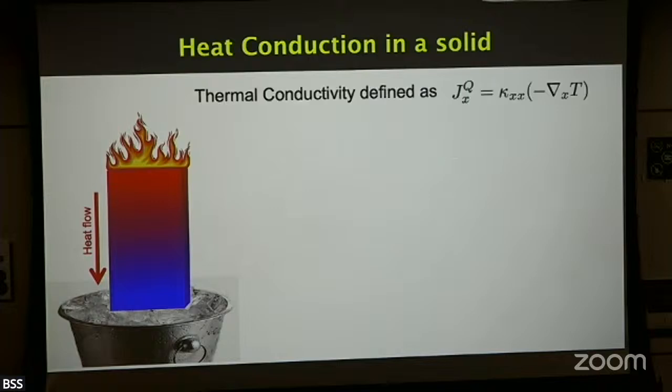And then the heat is going in, and so thermal conductivity, like last week, Brandon gave a very comprehensive plenary lecture about thermal conduction. And this is the Fourier's law. Your heat current in the x direction, I'm going to call this the x direction, and the temperature gradient along the x direction, that coefficient is thermal conductivity.